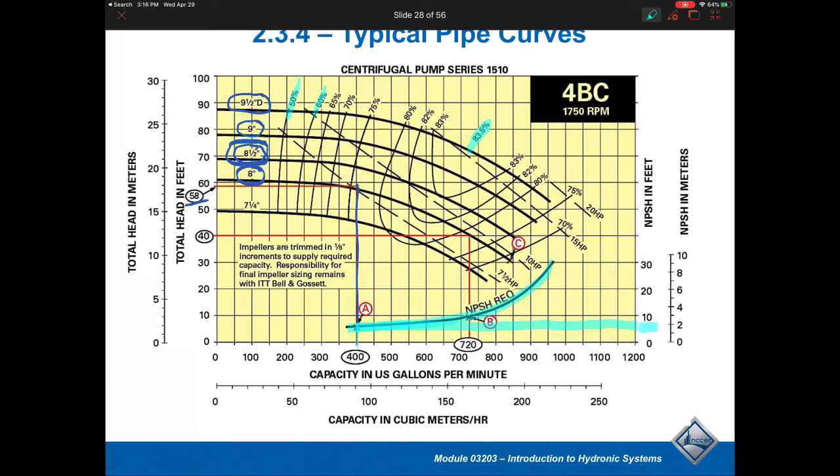We obviously would want a pump that has the highest efficiency possible, and that's challenging in some cases. If we're in the middle third range of a pump, we usually can get the highest efficiencies. If we run closer to this side or even further out here, as you can tell, the efficiencies are going to be decreased a little bit. So pump efficiency is important because it affects our energy consumption on the pumps.